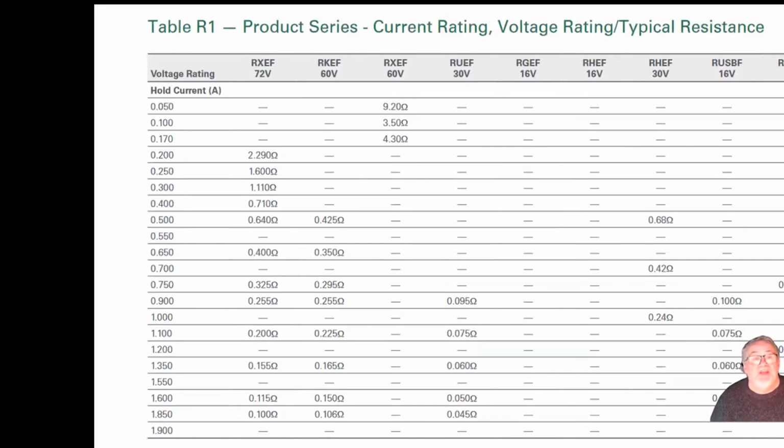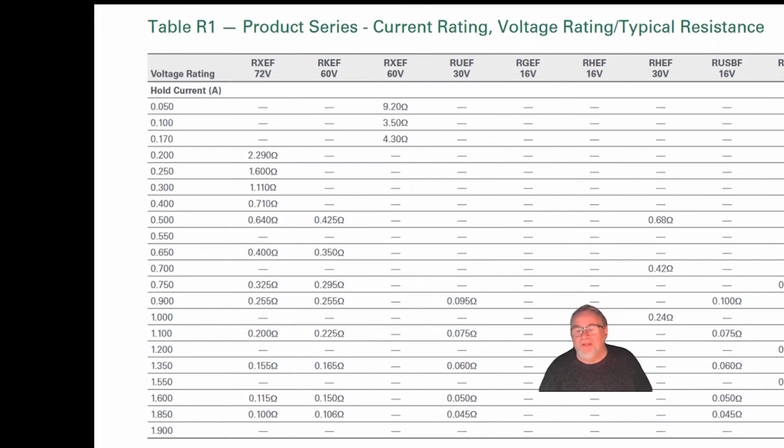There's part of the data sheet. The little fuse catalogue for these things is fascinating reading. It's another 20 pager and it's got all sorts of graphs and stuff. There's what they look like when they're not actually blowing. Down where my head is, you'll see that the low voltage ones are typically 1/10 of an ohm when they're doing their thing. So in the circuit, you've put 1/10 of an ohm in series with your circuit, so it doesn't really affect your circuit until it comes time to blow. And then it becomes 2 megohms and you can assume that your circuit is safe.